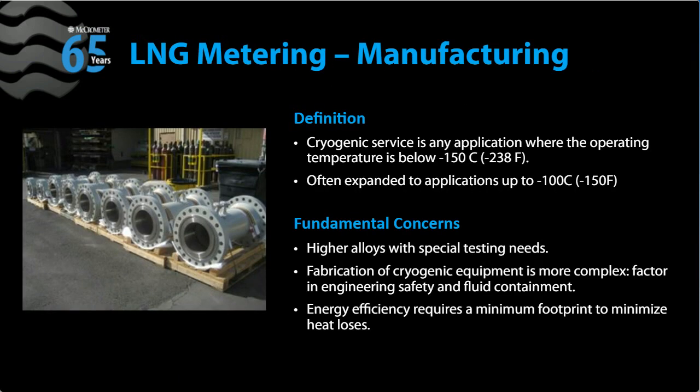So when it comes to LNG, the primary obstacle is manufacturing. LNG requires meters being in cryogenic service. Cryogenic service is any application where the operating temperature is below negative 238F, and sometimes they're expanding these applications to up to negative 150F.